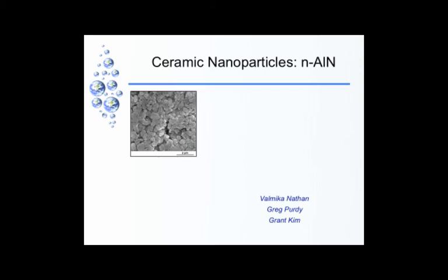Nanoparticles, on the other hand, because of their electrostatic repulsions and agglomeration, don't fill more than about 40 volume percent of space. So the idea of nanoparticles which pack poorly, increasing the packing density of another powder that packs poorly, hasn't been tried before.